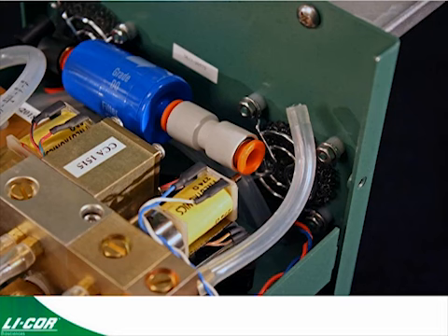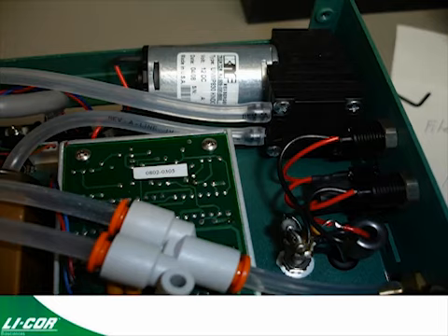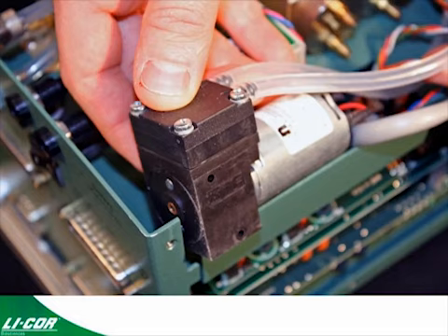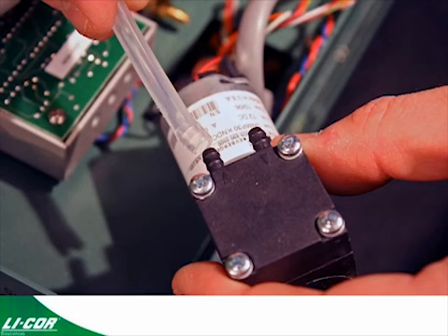Tubes 3 and 4 are more easily removed from the system by removing the pump. This pump is held in place by a single screw, which once removed, the pump can be repositioned and the tubing can easily be removed from the pump. You do want to take care not to damage the plastic hose barbs. If you do damage those plastic hose barbs, you will have to replace the pump.